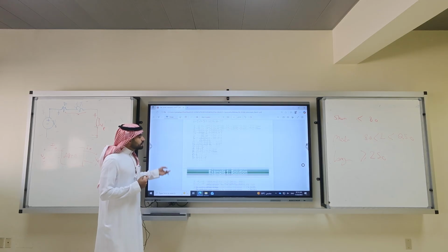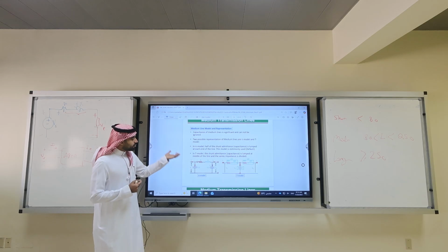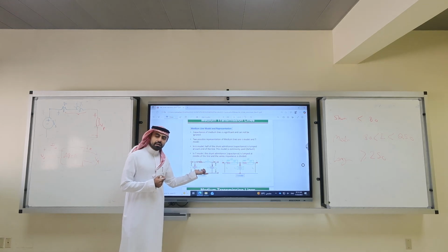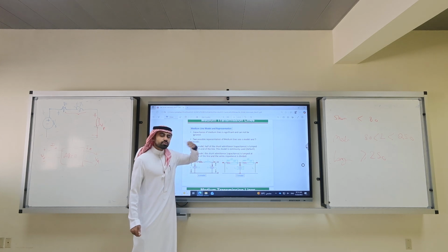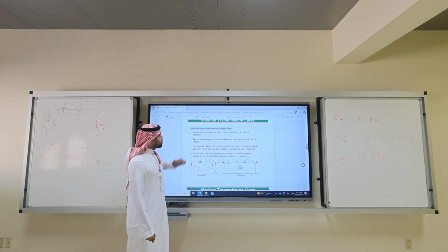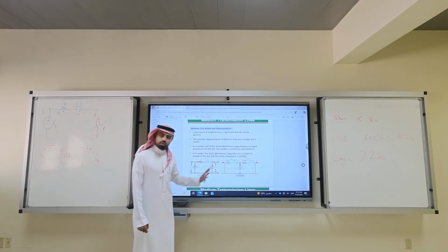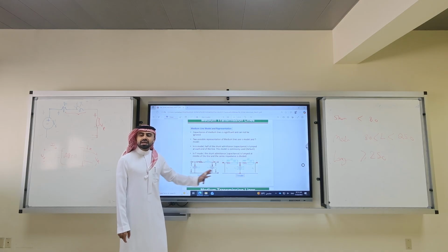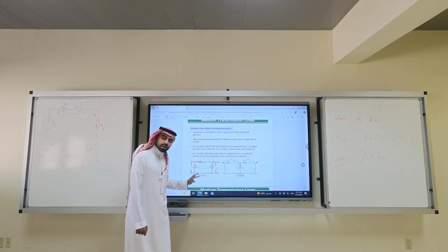In medium transmission lines, we have capacitors in parallel. You cannot ignore them. So the capacitance of medium lines is significant, and for long lines it is even worse, and cannot be ignored. So there are 2 possible representations. Both of them would give you the same outcome. Maybe this one is different than that one. Maybe there is a marginal error here.